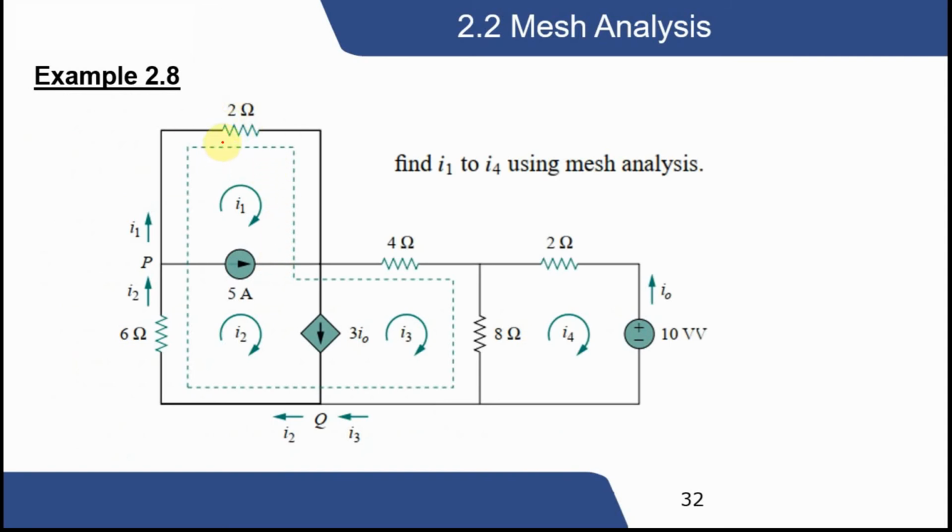Now we have another example. If we have two current sources, one independent and one dependent, inside the non-reference nodes, so one is a non-reference node, one is a non-reference node, and one is the reference node, how do we solve this? To solve this, first we open the current source. When you open the current source, you will see the network like this.